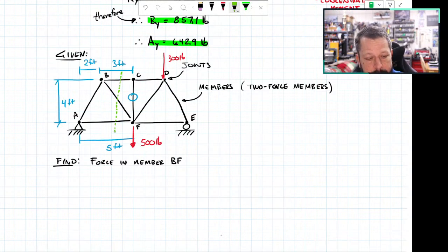And so that creates the section part of method of sections. I have 2 sections. I either have the section with joints AB or the section with CDEF. So I can work with either one of those sections. Sometimes, if it worked out to where I could chop off a piece of the truss, follow all the section rules, and cut off all the pins and rollers, then I may not need to solve for the reactions.